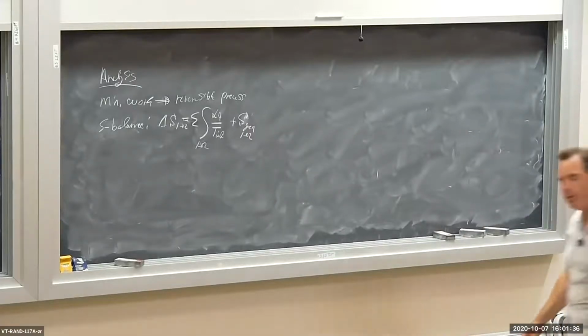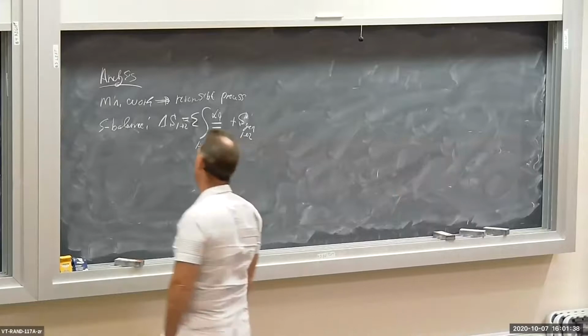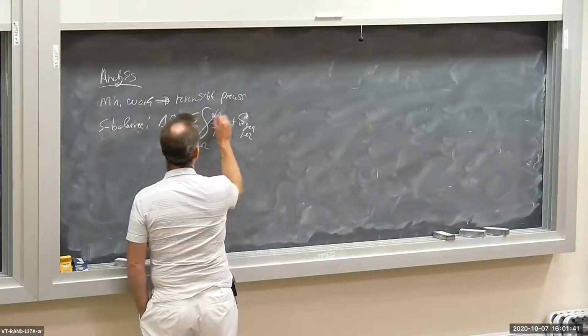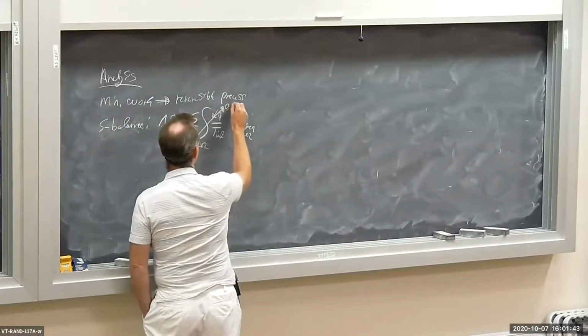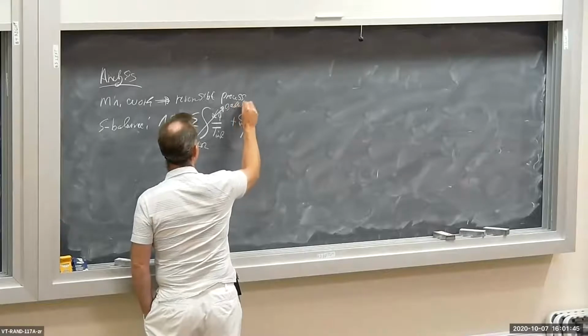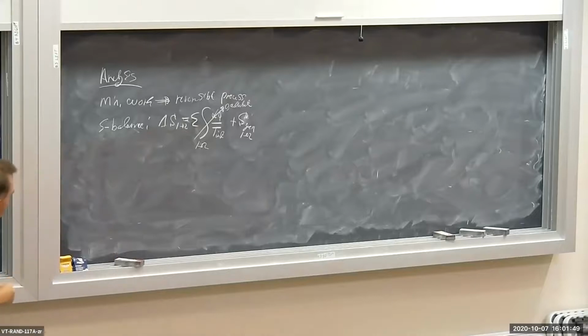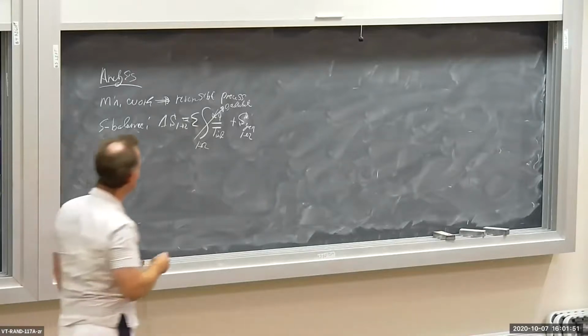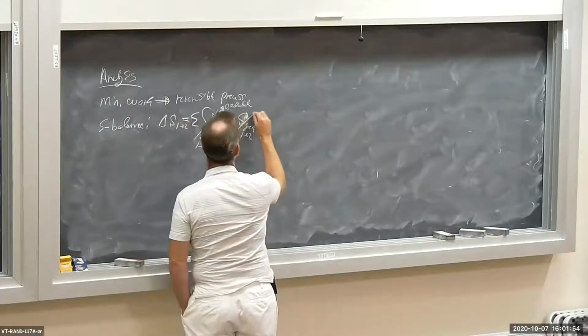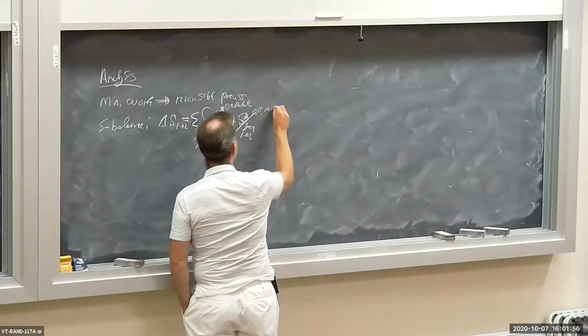Now the piston cylinder device is insulated, so we're going to assume an adiabatic process, so that term is 0. I'll write that in the assumptions in just a moment. And minimum work implies reversible process, so S gen is 0. Reversible.